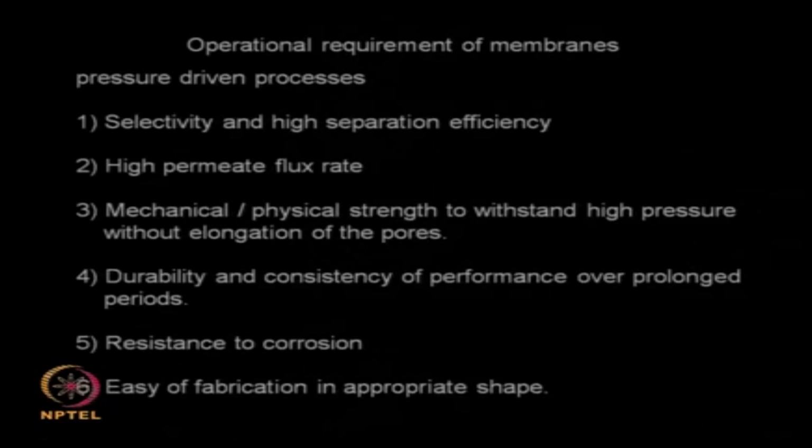There are many operational requirements in a membrane process, so you need to keep all those points in mind. We want to have very good selectivity, we want to have high separation efficiency. So this is the fundamental point. We want to have a high permeate flux rate, that means the rate of filtration has to be very good. The membrane should have good mechanical and physical strength to withstand the high pressure. Continuously you are operating at such high pressure, so your mechanical strength should be quite high. The pores should not get elongated because you are continuously applying a mechanical force.